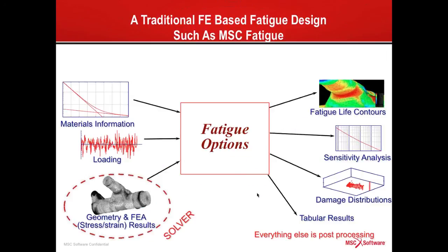And so really then it's a good point to look at how a traditional FE-based fatigue analysis works. MSC Fatigue follows these types of processes. Typically, in order to run a program like MSC Fatigue, you need three inputs. You need your material properties, you need your loading, and most important of all, you need stress information from a finite element analysis.